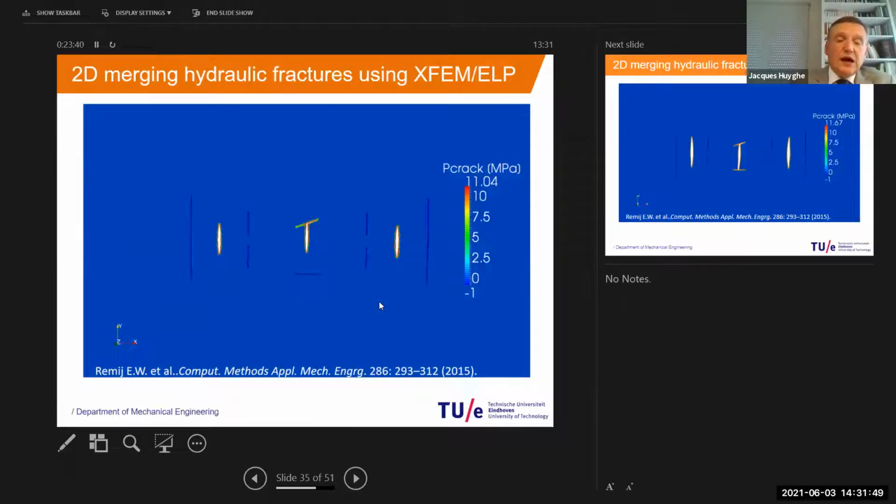So we see here how there is fluid accumulating inside the crack, and also at some point, as the crack propagates and reaches one of the faults, there is communication of fluid between the newly developed crack and the existing fault.